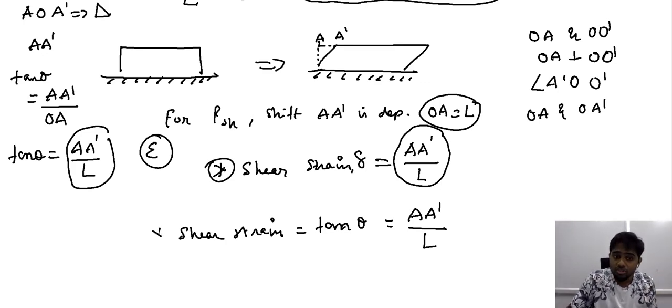And it is also possible for us to consider the loss in the orthogonality, meaning we can take the angle that describes the shift in the corners, and using that angle we are able to describe the shear strain. So the shear strain can be described both based on the shift in the corners or the angle that quantifies the shift in the corners.